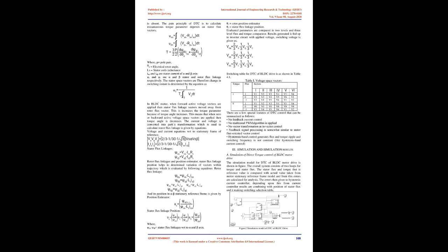The current and voltage are converted using Park's transformation, which is used to calculate the stator flux linkage, given by equations. Voltage and current equations with respect to the stationary frame of reference.